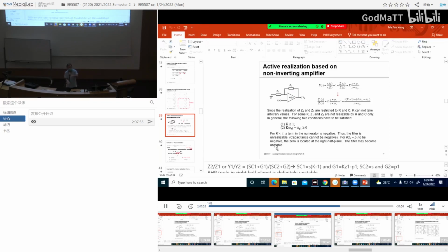So typically people say what? Depending. Some people say 45 degrees is enough. Sometimes we need 60 degrees. Sometimes, better still, 90 degrees. And if you look at the analysis, you'll find that how big a phase margin you have will determine your time, your unit step response. If your phase margin is too small, let's say 10 degree, 20 degree, 30 degree,